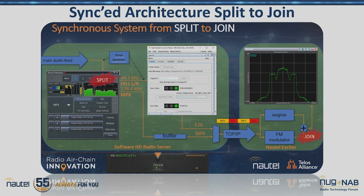And the key thing here was that from the audio split, where the FM and HD1 split, to where they rejoin in the RF waveform, we control all the delays in between. And that MPX E2X protocol in the middle, you see that transfer in orange and red on that screen.